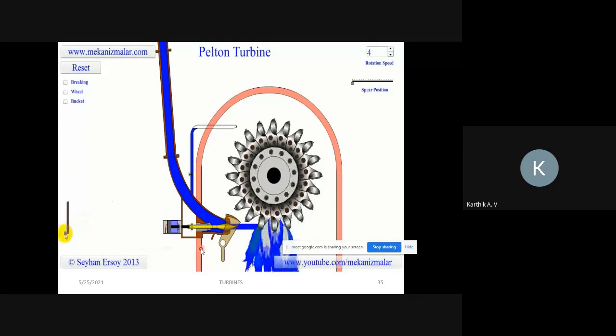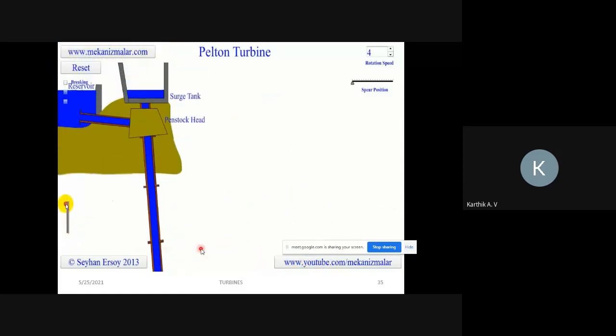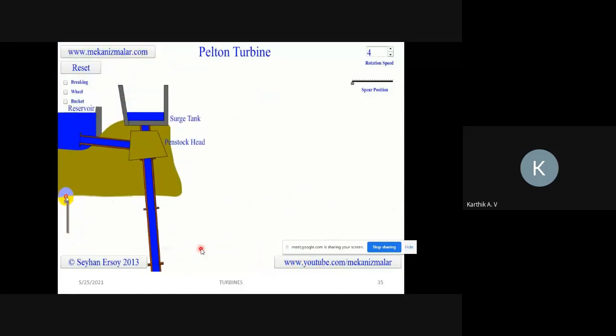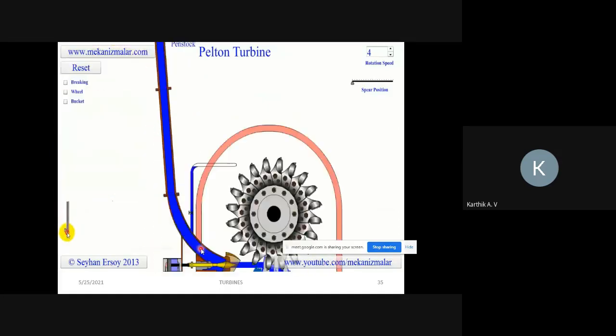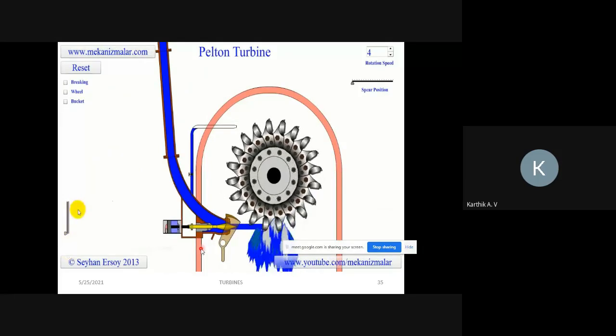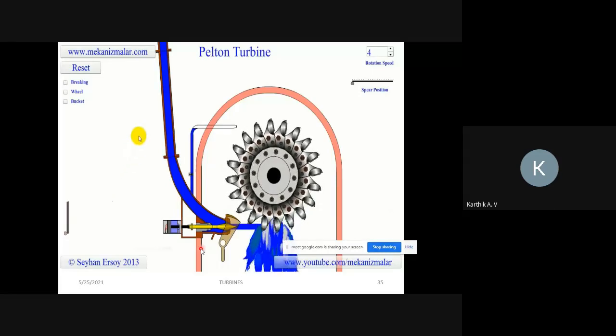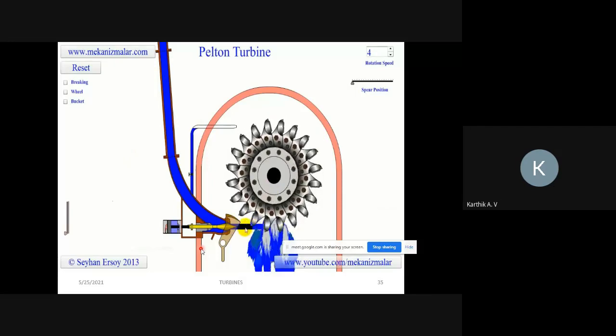Pelton wheels are the preferred turbine for hydropower when the available water source has a relatively high hydraulic head at low flow rates. The efficiency of these turbines increases with water head. There are 200 megawatt Pelton turbines in operation where the water head exceeds 1000 meters. Small Pelton turbines with enough water flow can operate as low as 15-meter water head.